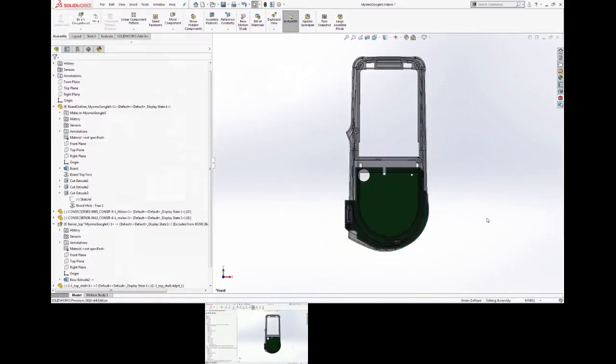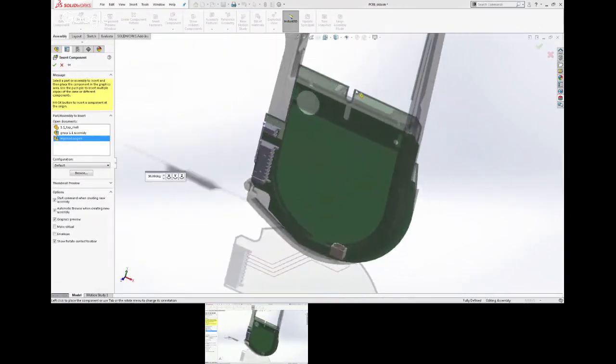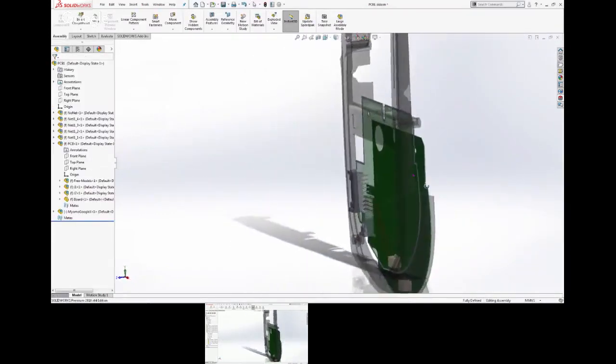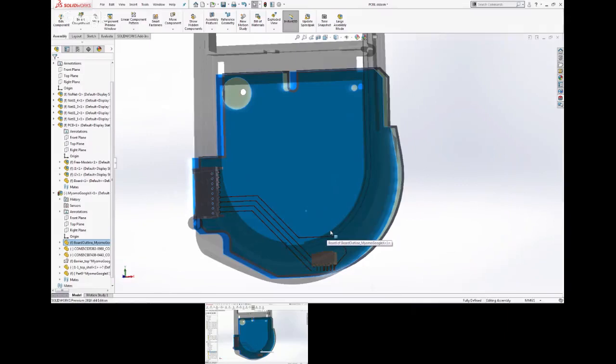It's actually the other way around. Okay, so here I can just drop it and then I can line it up. And then you can see copper. So I have one file, which is the subassembly that is linked to the PCB, and then I have the Parasolid, which represents the copper. I bring those two together, and now I can have a view and I see my copper and I see my components, the live linked assembly to my PCB. So if any changes occur, it will reflect immediately here if I accept those changes. So those traces are static because it's an export. Yeah, that's the one thing we still do statically, but we're working on bringing this information through the connector in future releases.